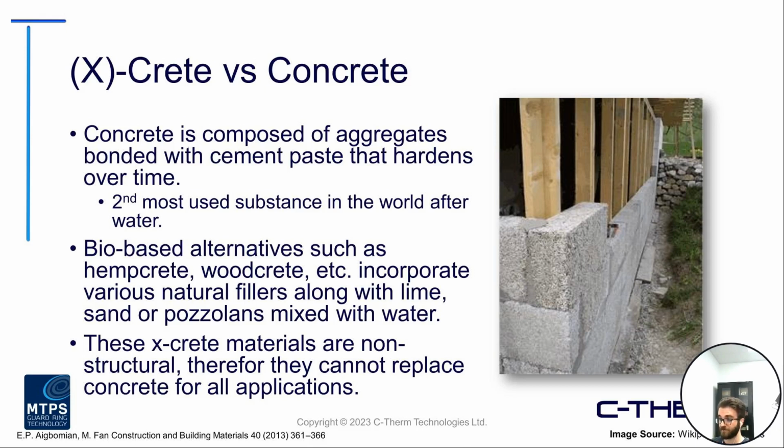But these bio-based alternatives, such as hempcrete, woodcrete, etc., essentially take the approach of incorporating various natural fillers in conjunction with lime, sand, or pozzolans, which is just another inorganic material mixed with water. Now, these X-Crete materials, whether it's hempcrete, woodcrete, what have you, they're non-structural. So that means certain applications with concrete, they're used as a structural basis along with their insulative performance. So these different bio-based alternatives are not necessarily going to be able to replace the traditional concrete in all areas